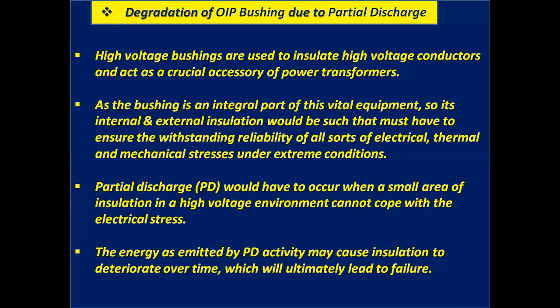Partial discharge occurs when a small area of insulation in a high voltage environment cannot cope with the electrical stress. The energy emitted by the PD activity may cause insulation to deteriorate over time, which will ultimately lead to failure.